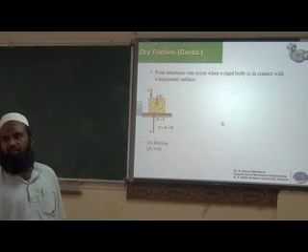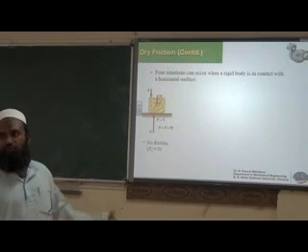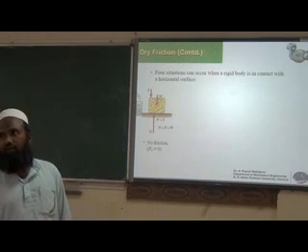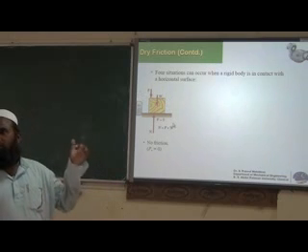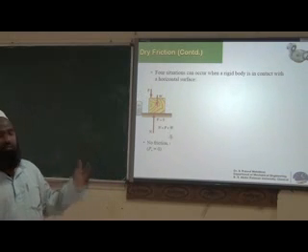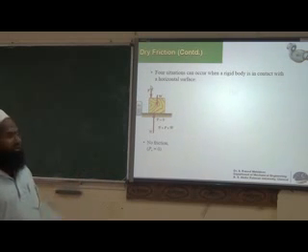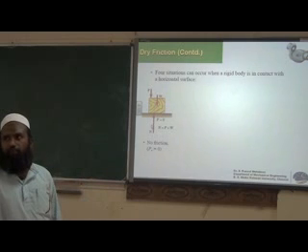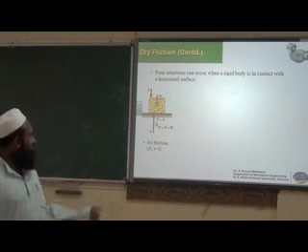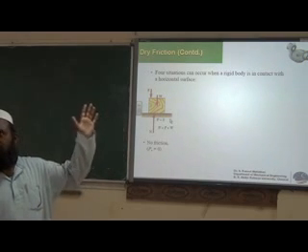There may be four situations in our friction. You have a weight W with another additional force P. There is no horizontal force, so no motion, and no frictional force also. The total downward force is resisted by the normal reaction N. So N equals P plus W. This is one condition where there is no horizontal force, no motion, no friction.